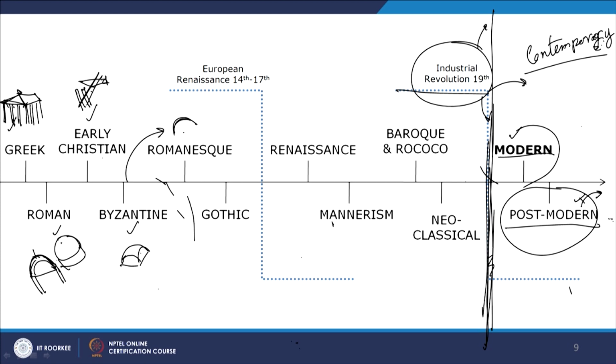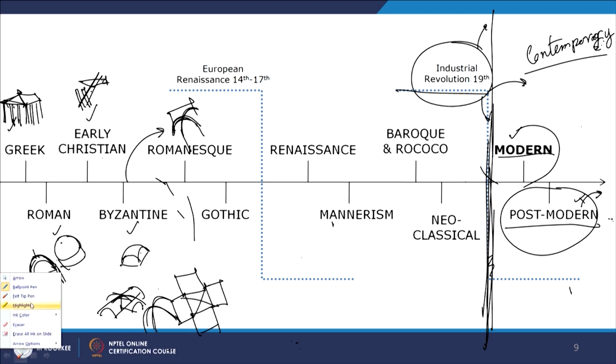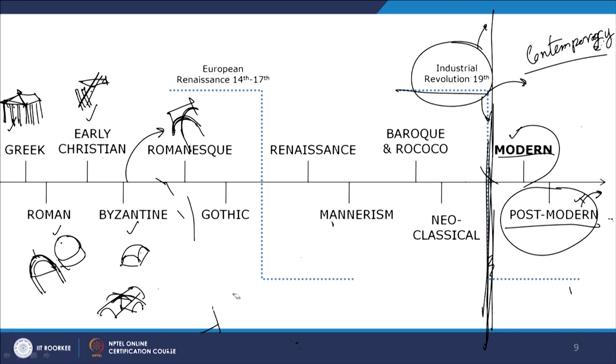So there was a vault. Then if they make a cross vault, making a church becomes very easy. So this cross vault is in plan. You will see this cross is going. Now you can add this part in this part, and then you can have a vaulted structure, but two vaults are penetrating each other. So that's what you can get, a cross vault. Here you will make the cross vault, and two vaults will penetrate each other. That's what they made in the Romanesque, this cross vault.